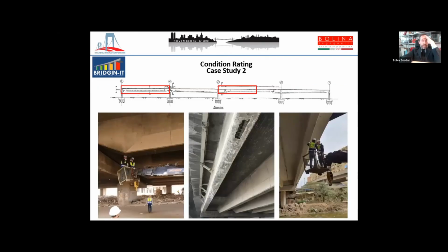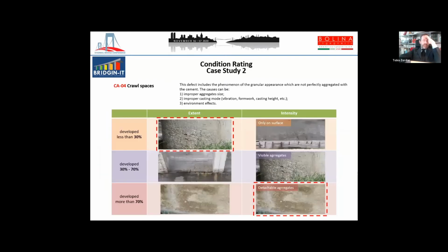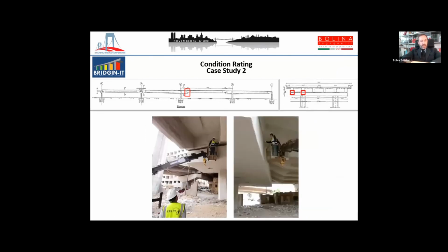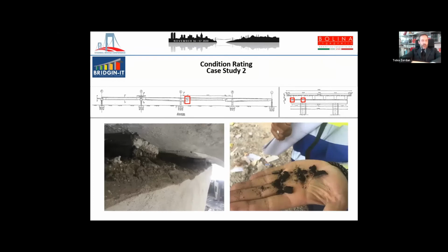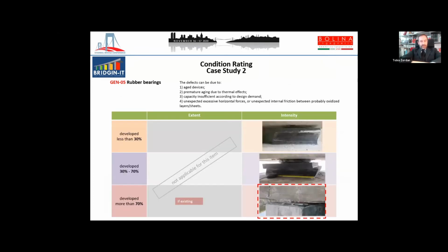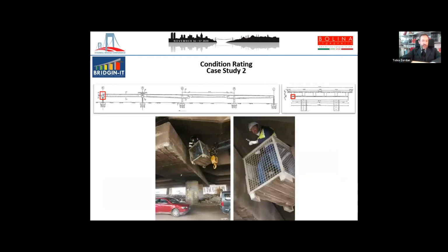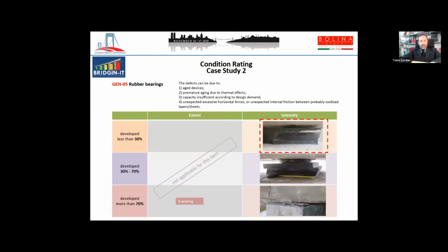Again, the condition rating, inspection here about the girders, with, as I anticipated before, the extent and the intensity of any kind of defect. And the combination of extension and intensity is giving you the actual rating. The bearings, we saw there were completely burnt bearings. Others were in less severe conditions. Again, the bearings,